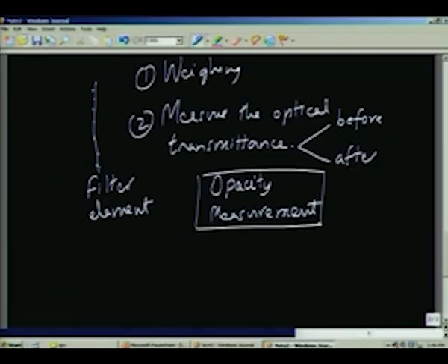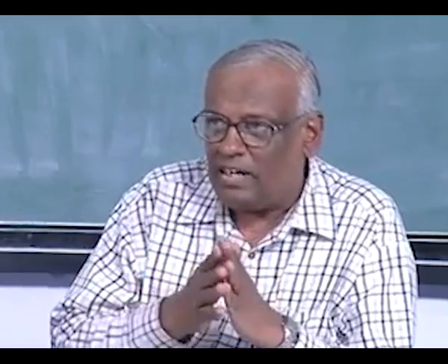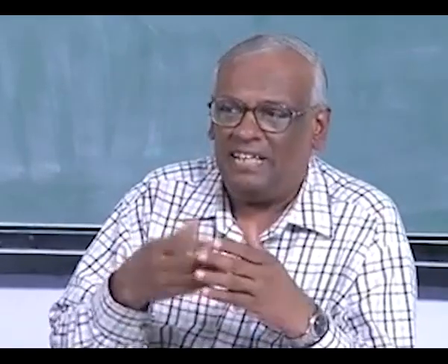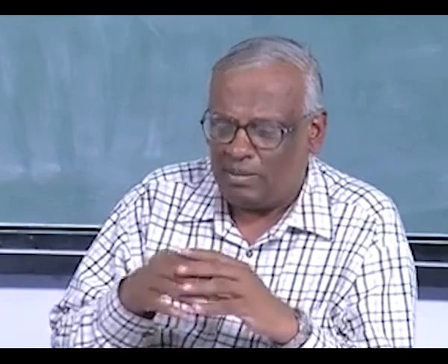So, opacity measurement can be done in this case also, but what I will do is I will describe an opacity measurement in the in situ case, because there we are not collecting the material. Here we have a filter element, and you just put the filter element in the path of a light beam, find out the transmittance before and after, you get the opacity. But this opacity is now related to the total amount of material collected over a given amount of time, and therefore, you have to relate it to the concentration of the dust or the particulates in the original gas sample by using a little bit of algebra.